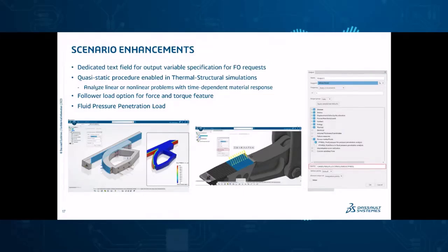We've had a lot of requests to enable quasi-static procedures for coupled thermal structural simulations. This is useful in situations where there's time-dependent material responses like creep or viscoelasticity. And so this has now been added.